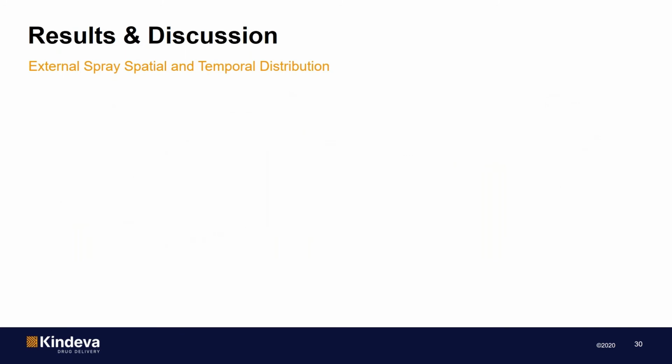Now, moving forward, to gain confidence in our spray model, we compare the CFD prediction against our phase Doppler anemometry measurement of the spray. I should mention that the measurements are conducted on a spray injected into still air, whereas the CFD model, as you saw, has the spray injected into a confined space with finite co-flow.